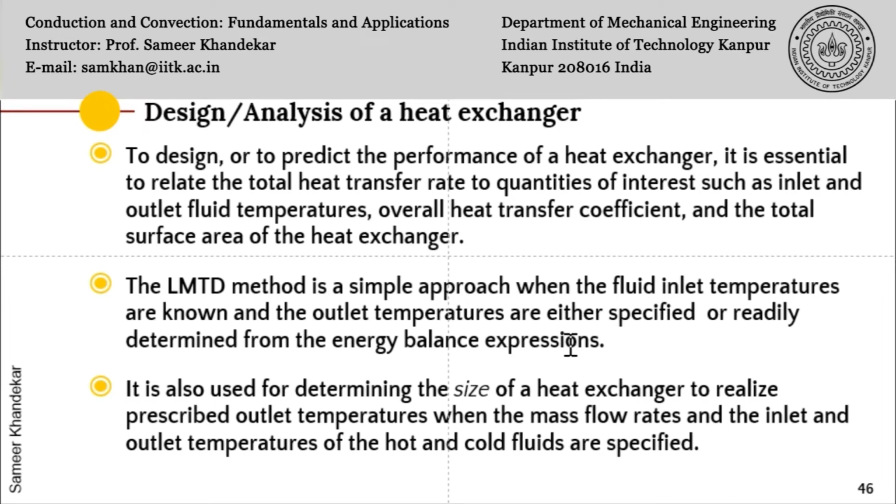So when these temperatures are known, the inlet temperatures and the outlet temperatures, or the expected outlet temperature, if this is specified, then we will use, as I said, the LMTD method, or the logarithmic mean temperature difference method, for this class of problems, the sizing problem. Then it is also used for determining the size of the heat exchanger. That is what I am saying, sizing, to realize the prescribed outlet temperature.